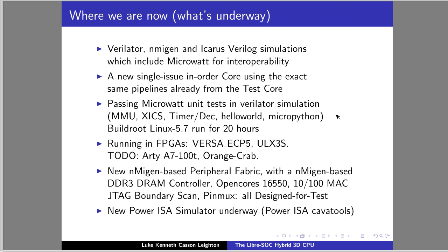So we've actually had to put in something that looks similar to a 6600 scoreboard to track a vector of register usage per pipeline, which then gets merged back. It's complicated. I wish we didn't have to do it, because it's actually going to take up a lot of gates. But it is what it is.